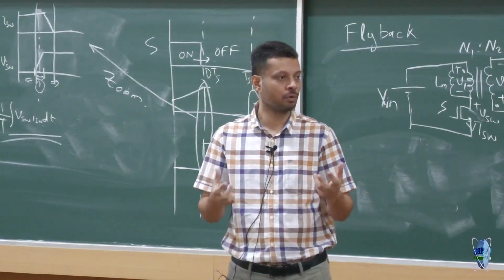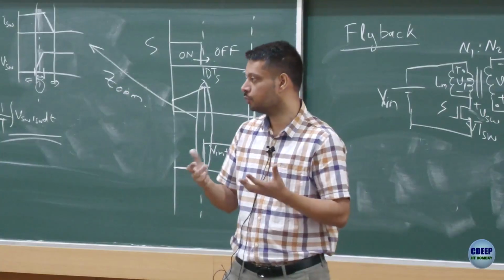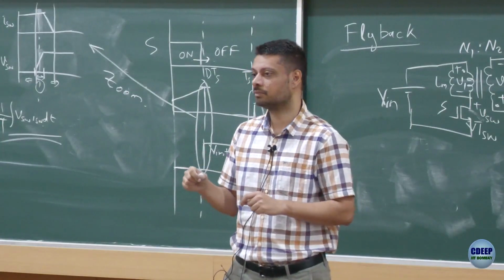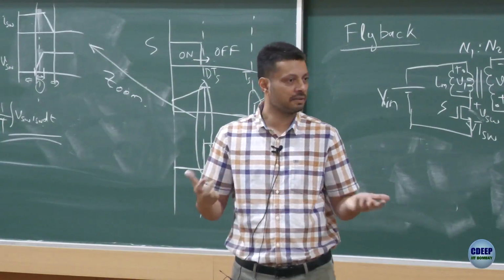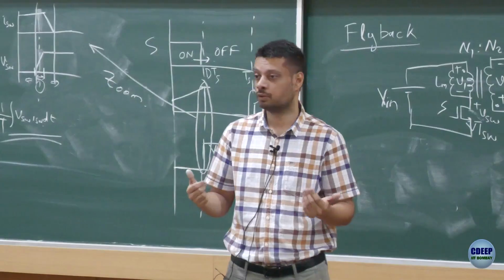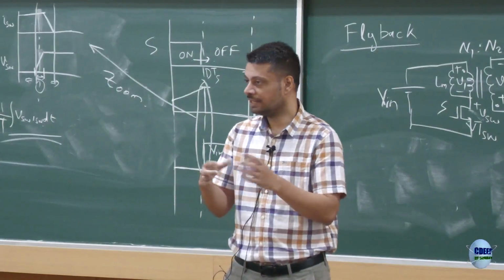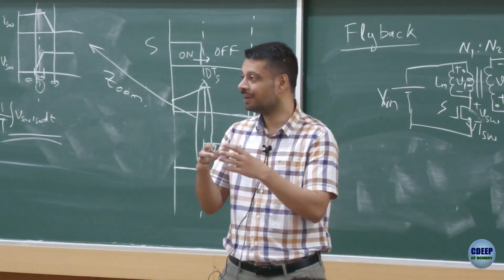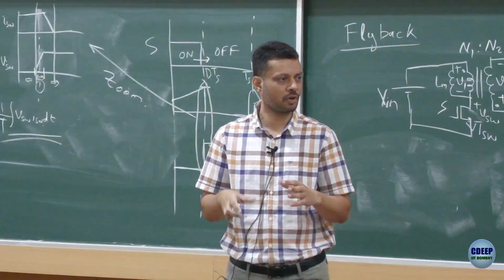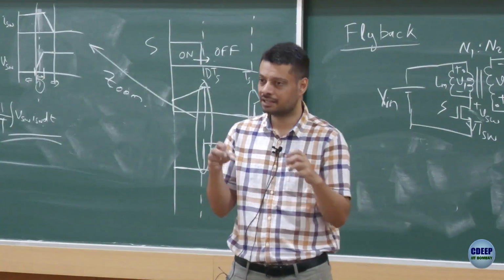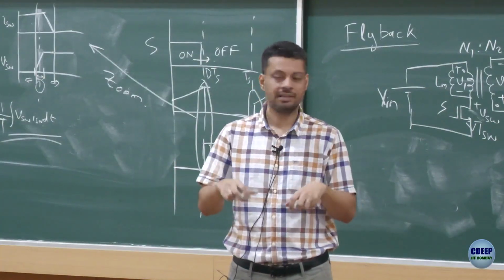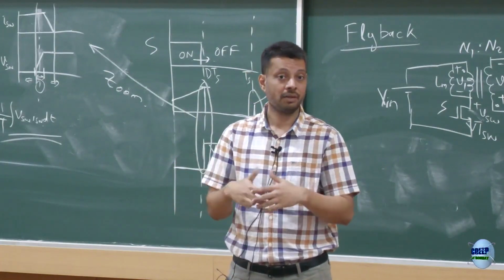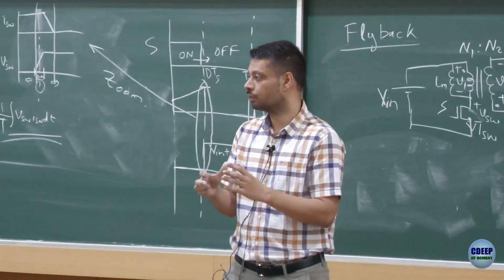The microcontroller would require 3 volt supply to operate. You may have some op amps, or comparator circuits, or logic circuits which would require 5 volt, or maybe plus minus 12 volt, plus minus 15 volt. So in any electronics product, you don't require only one voltage, you require multiple voltages. If you open an air conditioner, for example, internally you would see so many chips. Some chips would require 3 volts, some 5 volts, some plus minus 12 volt. So there are multiple voltage requirements.